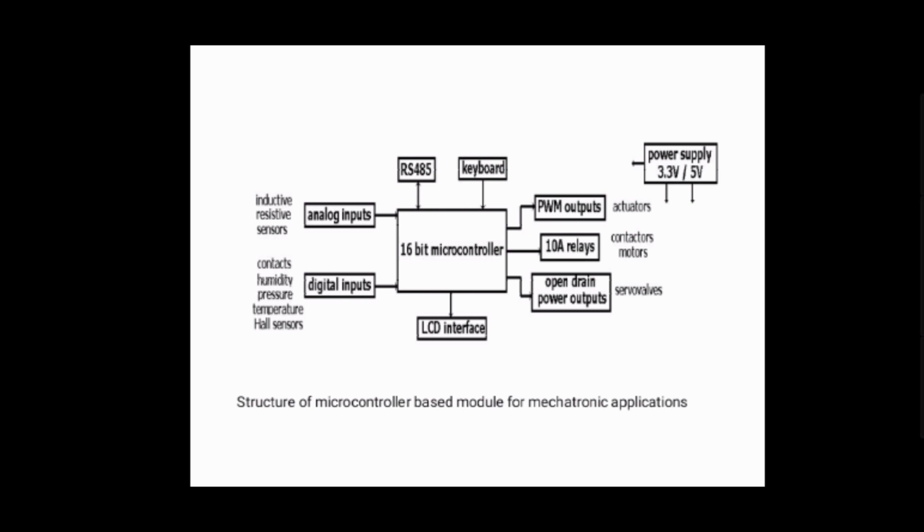You could see here it can be connected to the 10 amp relays, which in turn can be connected to the contactors, motors. Similarly you have open drain power outputs, which could be connected to the servo valves. And here you could see an RS485. It is a serial standard. This can be connected to the PC, where it can communicate to the outside world.